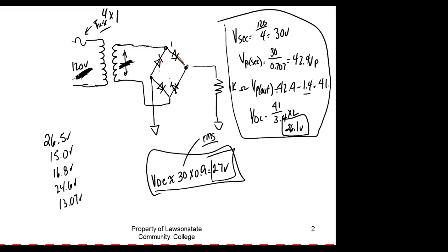If I'm putting 200 volts on the thing, I don't even take out the 7/10 of a volt anymore, because that would be ridiculous. So usually anything above 100 volts, we forget about the 7/10 and use what we call ideal approximation. You use third approximation if you're an engineer, if it means anything, but very few engineers do that, because in electronics we're dealing with so many different things that have tolerances on them, right? You understand that?